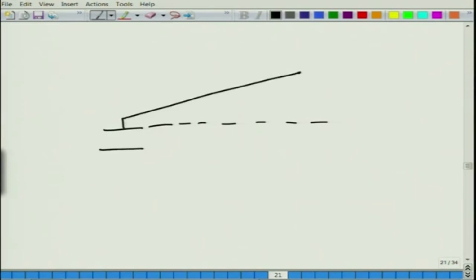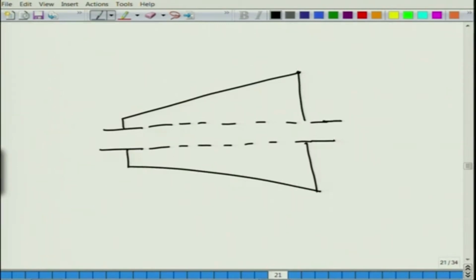So, a clever way is basically to combine this into a composite structure like the one that I discussed, and actually one can also use a conical one. There are things like CCTRs, conical concentric tube resonators. Let me just draw, although I can't analyze it right now. There are configurations like these which are used in two wheelers. So, mufflers which are like this can be fully perforated along the length or partially perforated. That is a very interesting area of study. A person can do some good research based on higher multidimensional wave propagation in such a system, especially when the flow is there.